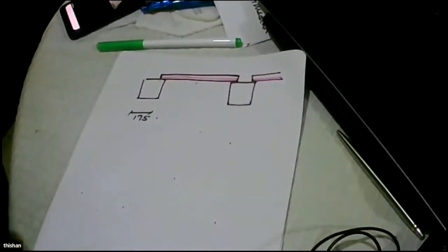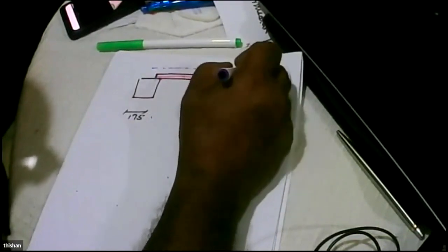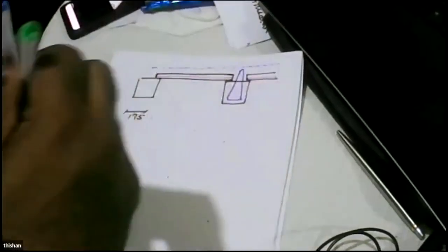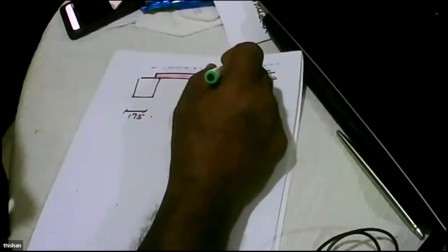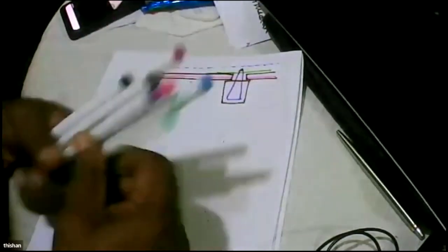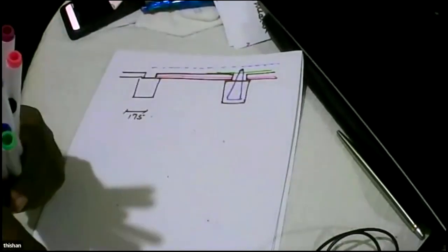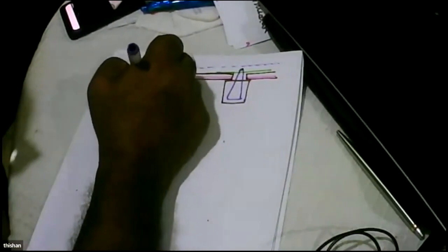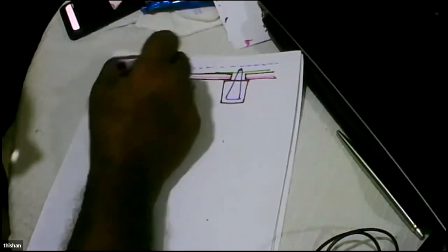Now somebody might argue, this is the top surface, how are we going to lock it? So we thought, okay, let's have this triangular shaped reinforcement. We can put an 8 millimeter bar or a 10 millimeter bar. But when you do this, you will find that this reinforcement is having a lot of cover. Then we thought, let's have a reinforcement at this level to lock it, and the continued reinforcement to go above it, so it will act as a top reinforcement.